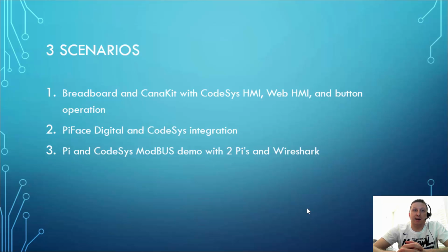And what I'll be doing is interacting through Modbus. As you know, that's port 502 that we used before, and we showed how it was insecure. If someone went on there, they could do things over port 502 because it's clear text, and you can see what's going on with that. So I'll be using Wireshark just to sniff out and see the interaction on the Modbus traffic. But I'll have them connecting. I'll send some output, and then we'll be able to see what's received on the other end.